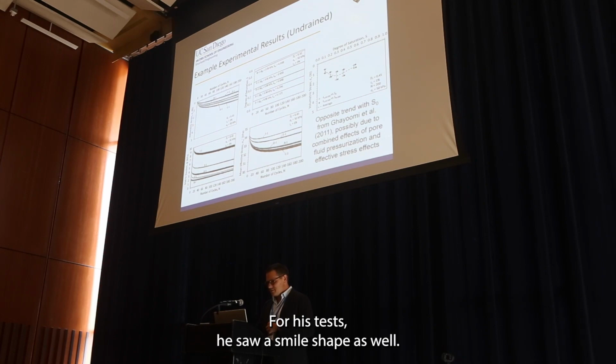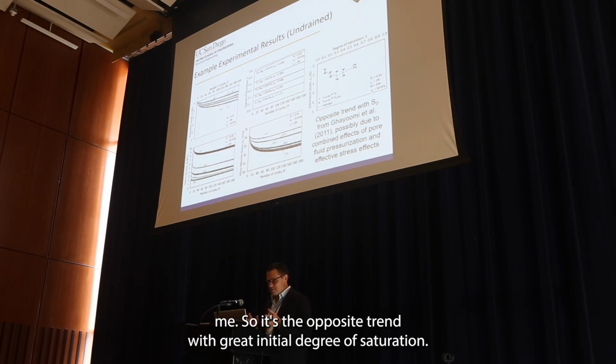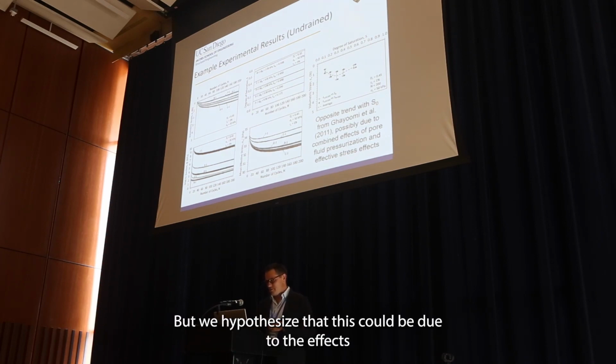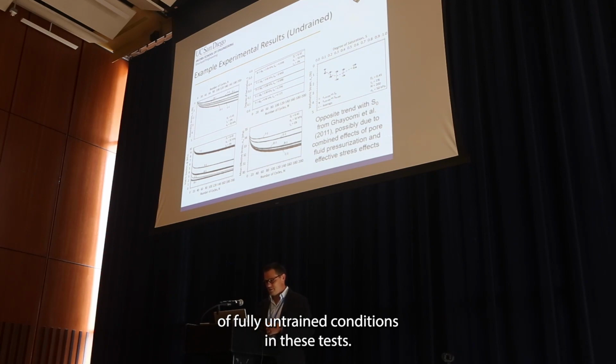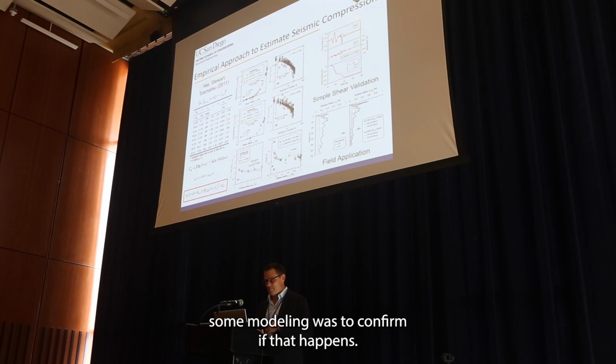For his tests, he saw a smile shape as well, but this is because the volumetric strain is aligned downwards in this figure. This would actually be a frown if you compared it with the results from Gayoumi. So it's the opposite trend with initial degree of saturation, but we hypothesized that this could be due to the effects of fully undrained conditions in these tests. So one of the reasons that we wanted to do some modeling was to confirm if that happens.